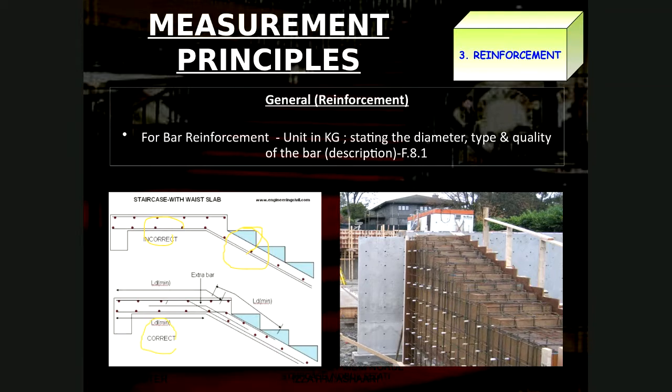If you look at the layout, I use different colors, maybe red color. You can see here, this is the bar reinforcement until here. So this actually belongs to the bar reinforcement in the landing slab. But even though this one belongs to the landing slab, you can see it overlaps with the bar reinforcement, or with the component inside the staircase. Same goes to this bar. This is the bar inside the landing slab, but it is overlapped with the steps in the staircase.